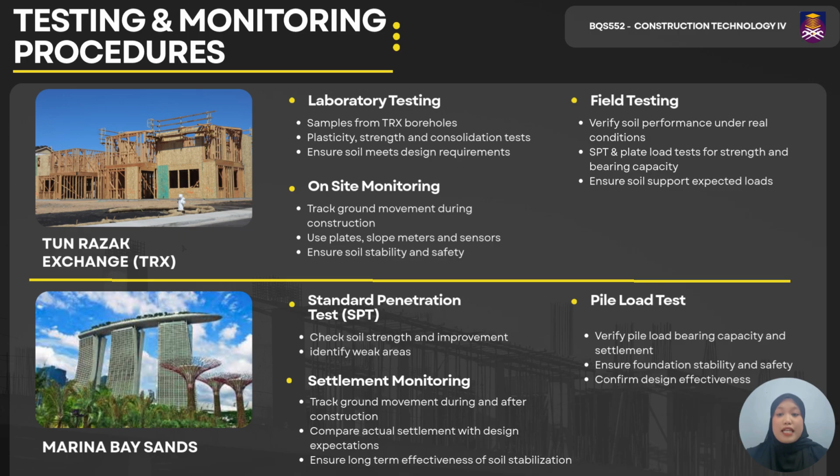At Marina Bay Sands, standard penetration tests and pile load tests confirm soil and pile performance. Settlement monitoring ensures treated soil maintains strength under real loads. Continuous monitoring in both projects allows early detection of issues, ensuring safe and effective soil stabilization.